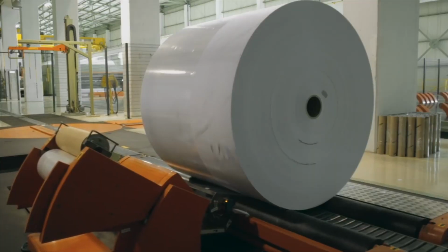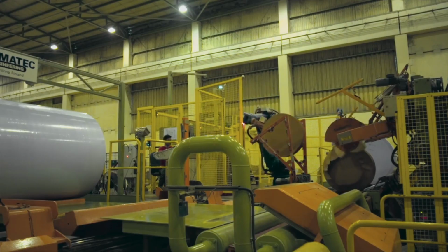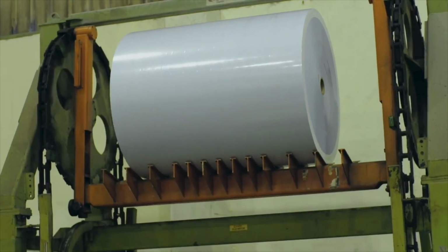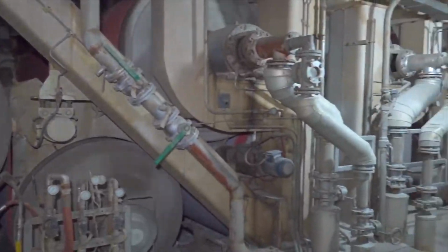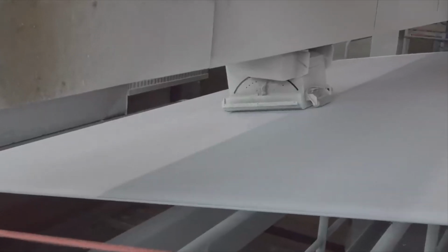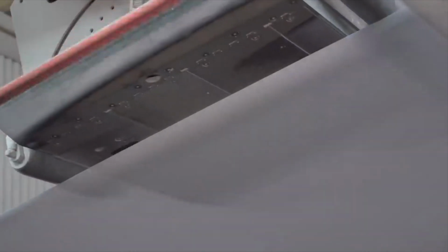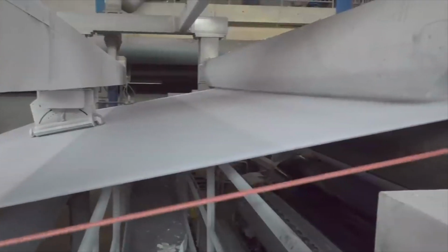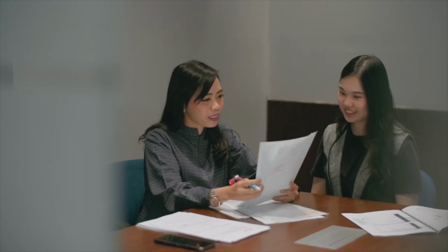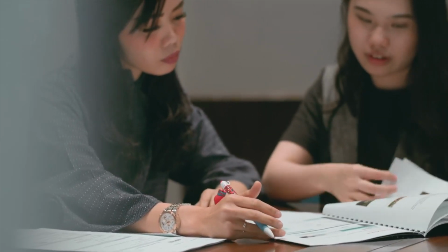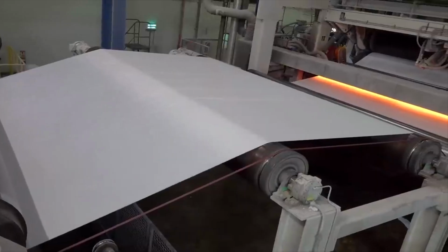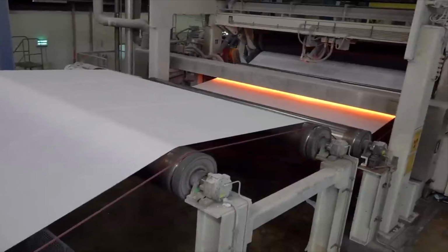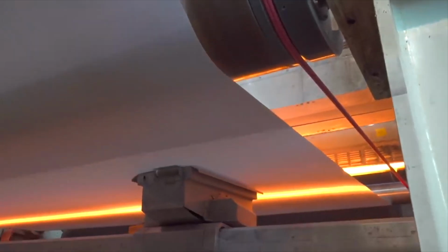Calendering is an optional finishing process that further smooths and modifies the paper surface for applications requiring a glossy appearance or enhanced printability. In calendering, the dried paper sheet passes through a set of hard pressure rolls, which compress the paper web and smooth out its surface texture. The pressure applied during calendering reduces pitting and smooths fibers within the paper sheet. Calendering would be used in production of glossy paper for magazines, posters, and brochures, as well as coated papers for high-quality printing. The resulting surface improves reflectivity, opacity, and print quality. However, calendering is unnecessary for uncoated copy papers or tissue products, so it is an optional stage based on the desired outcome.